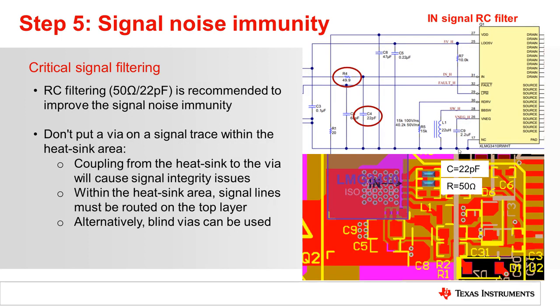Lastly, let's look at the filtering of the critical signals. In the case of our LMG3410 family, the IN pin, which carries the input signal, is a critical one. An RC filter of 50 ohm and 22 picofarad is recommended to improve the signal noise immunity.